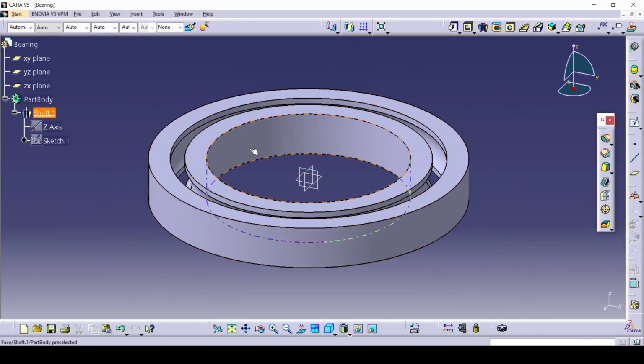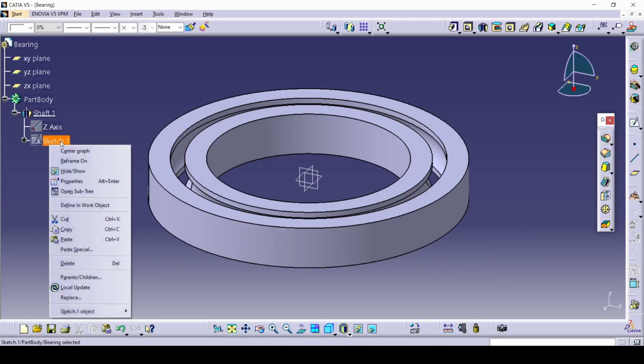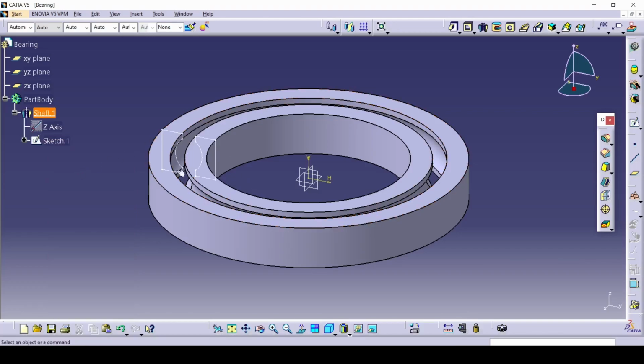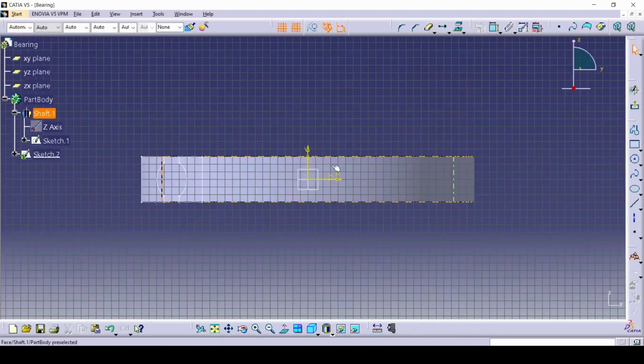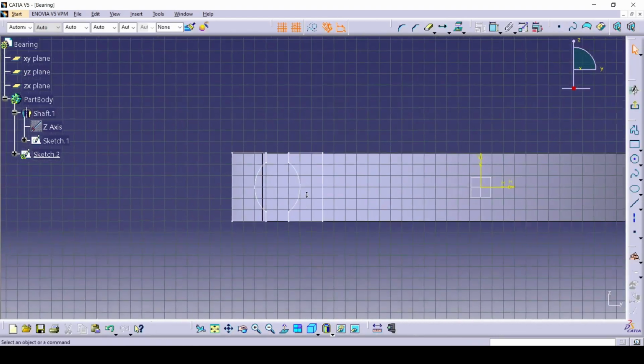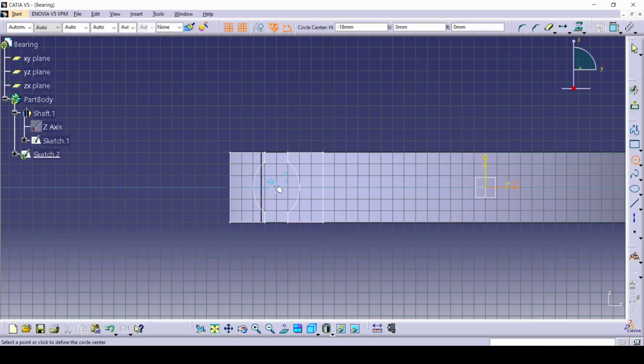So to simplify the drawing for the ball, let's just go to this sketch that's hidden now and press right click and find the third command, either show, or press just H on your keyboard to show it again. Then go and make a separate sketch, which is important. Do not double click this, make a separate sketch. So select the plane again, the Y and Z plane, select it, go here, zoom in a little bit, and make a little circle. It has to be centered.